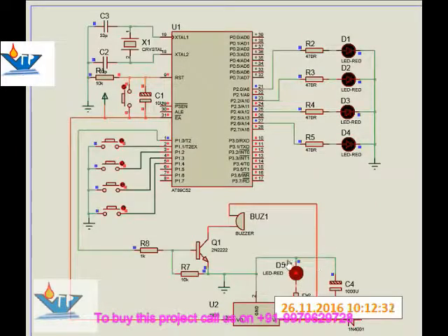The second pin is ground, the first pin is input, while the third pin is output. It is fed to the supply pin, and pin number 40 is hidden in Proteus. Also pin number 20, that is ground, is hidden. The positive 12 volt is available directly here at the buzzer, while the negative is available with the help of this emitter collector junction, but it is off now.